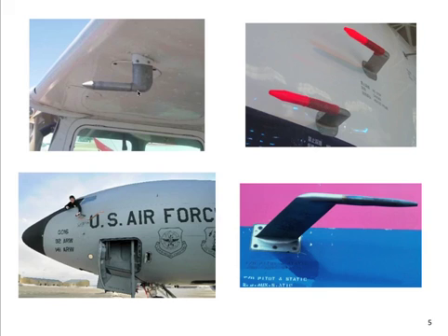So this is used to measure the airspeed of the plane. And we need to use both a static and a dynamic pressure tap in this case, because we can't just use atmospheric pressure and take the standard atmospheric pressure value, because the plane is, of course, changing elevations, and the reference pressure is changing as the plane is flying at a higher altitude. So we have to measure the static pressure of the air and also the dynamic pressure of the air and obtain the velocity by the difference of the two.